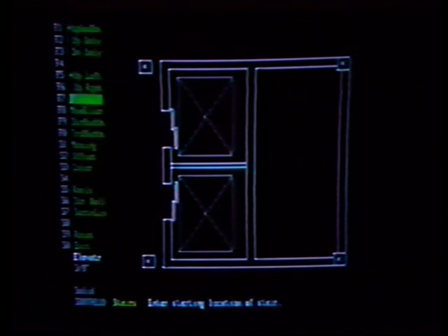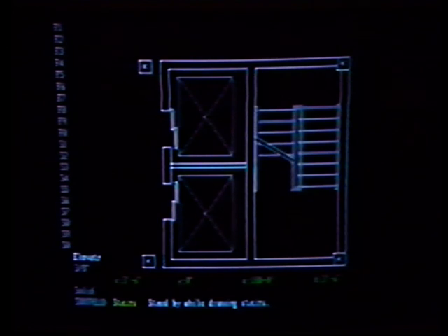we'll go to the menu right below Elevator called Stairs, which allows us to produce 3 kinds of stairs: stairs that go up and down, stairs that go up only with a section break, and stairs that go down only with no section break between the stairs. For our purposes, we'll use up and down stairs, and I can create those stairs just by setting up the number of risers, the stair width, and the treads, and then locating where those stairs start, let's say here, and which direction they face. And DataCAD AEC will take over and construct all the parts of the stair, the risers, the treads, the railings, even the section breaks between the up and down stair.